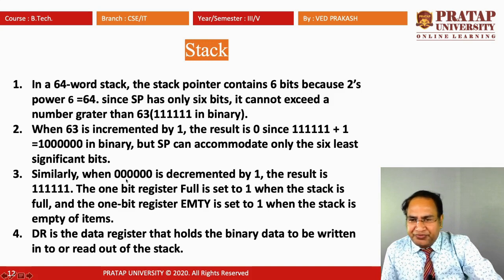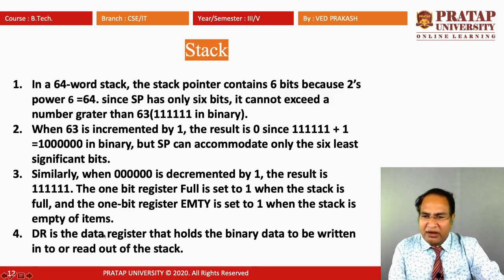Similarly, when 000000 is decremented by 1, the result is again 111111. The 1-bit register FULL is set to 1 when the stack is full, and the 1-bit register EMPTY is set to 1 when the stack is empty. So when the stack is empty, the EMPTY flip-flop value is 1. Here we use another register, DR. DR is the data register that holds the binary data to be written to or read out of the stack.